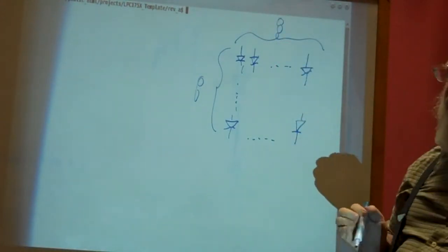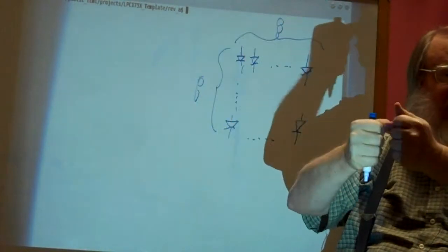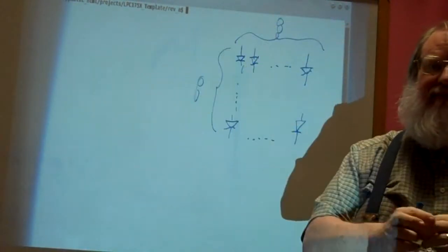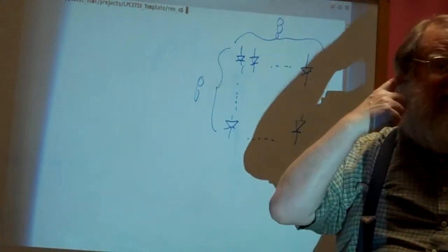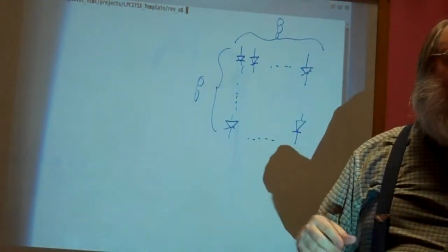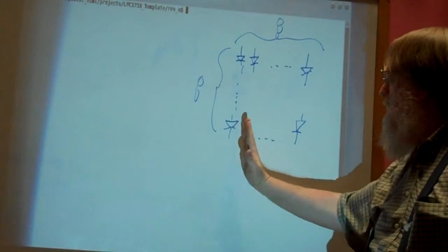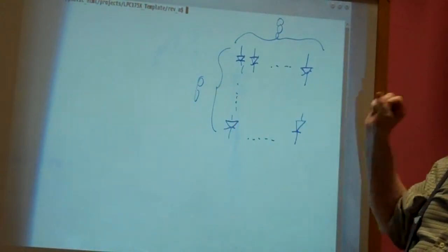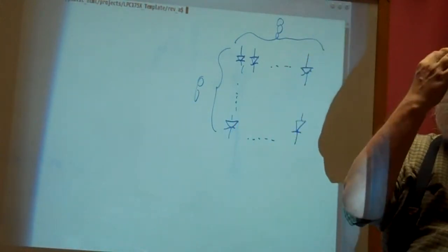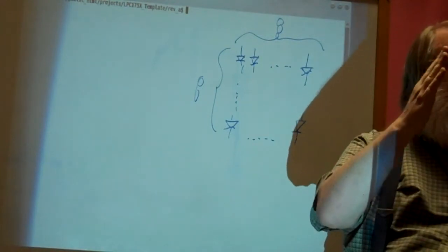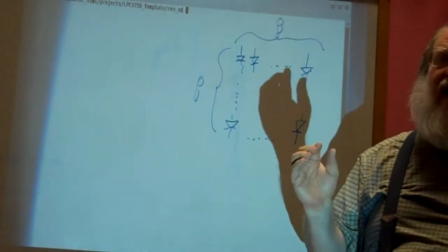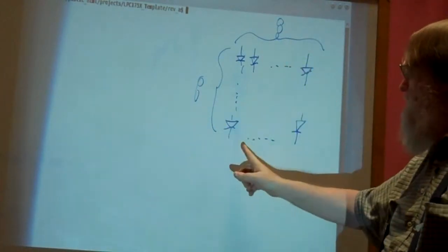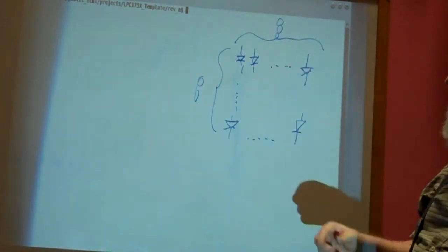Now, most of you have seen those scrolling LED panels. I actually think there's some of them around. I think there's one out on the other side. Well, the way those work is they actually light one column at a time, and they flash it. And because of the persistence of vision of your eye, you don't see the flashing. It's the way televisions and movies work as well. So what we want to do is design a system that can do that.